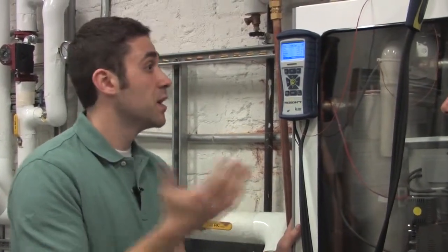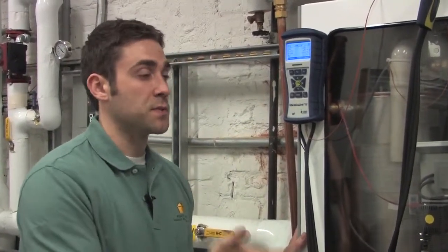Should every boiler technician that starts your furnace up every year be doing this? They should be doing this, right? Things change. Components get dirty. There's a lot of dust, construction going on in homes, or if you have a dryer downstairs, a lot of times you get all that lint pulled into the burners, especially if they're atmospheric. So having a regular clean and tune, at least every 2 years. I mean, if not every year.